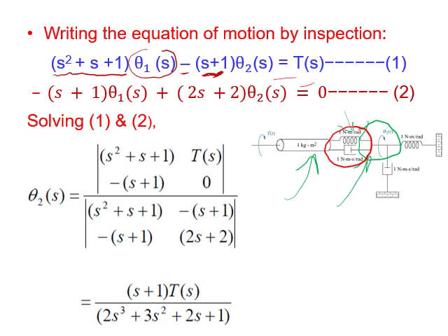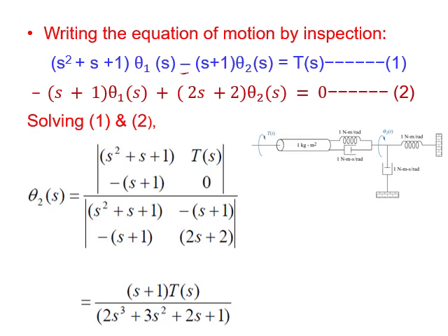The second equation will be very similar. So we will start by negative the link between theta 2 and theta 1. Remember, I am putting it this way because I want to keep the right order. Here theta 1, here theta 1, here theta 2, here theta 2. That's why I start with the negative. So it's minus the link between theta 1 and theta 2 into theta 1 plus the whole impedances connected to theta 2.